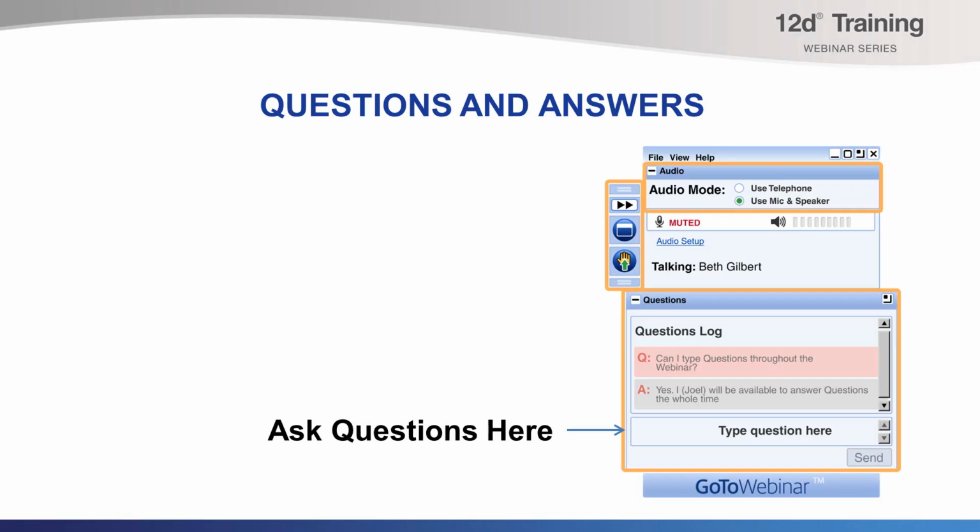Thanks, Paul. So Rosen in New South Wales has asked, when using the attribute manipulator file to translate attributes from vertex to string, what happens if the vertex attributes are inconsistent across a string? If they're not there, they'll just be skipped. They just skip the attribute altogether. Hopefully that answers your question. If it doesn't, you can fire us through an email and we can follow that one up.